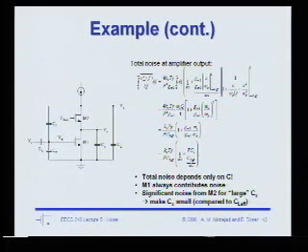Great, this result makes sense. KT over CL, because the GM cancels out with the noise GM. This extra factor, because we get extra noise from the cascode. And this F is my feedback factor. So here's one important point. This is not the feedback factor for the closed loop amplifier. This is the feedback factor seen by the noise transfer function. Okay, any questions about that?